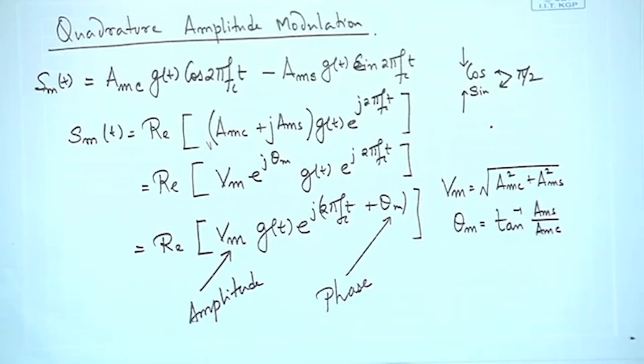Whatever it is, in the pulse amplitude modulation, you had only one signal to choose from. That means you would choose the amplitude only, and there was only a cosine, so that was the basis function. In case of phase shift keying, again you had only one parameter to select, that is the phase, and you chose one of the phases from a whole set of phases available. That did result in different amplitudes in the I and the Q, but they were constrained by the phase.